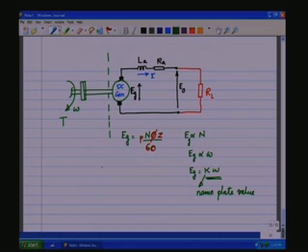Which means that T is proportional to the load I, because we saw that the load I is going to give an opposing torque on the mechanical side by the Lorentz force, and the torque has to overcome that opposing torque, which has to be proportional to I, and T will be equal to the same k into I, which is provided in the nameplate. Okay. So, these two are the connecting links between the mechanical and the electrical side.